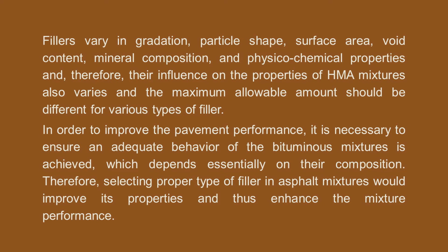Fillers vary in gradation, particle shape, surface area, void content, mineral composition, and physicochemical properties, and therefore, their influence on the properties of HMA mixtures also varies, and the maximum allowable amount should be different for various types of fillers.